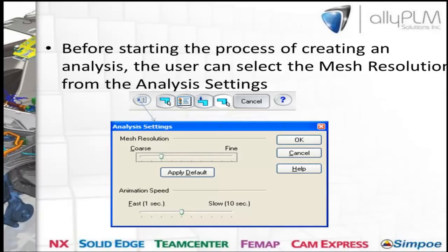The reason I do that is because you can compare these results. The finer the mesh, the more accurate the results are. FEA is an approximation technique. So whenever I change the mesh resolution and get my results, I just make sure that there's not much difference between the 2 cases, and that's what I try to achieve.